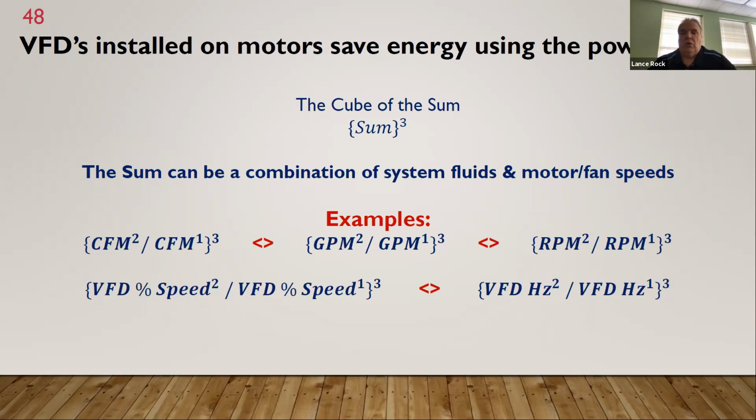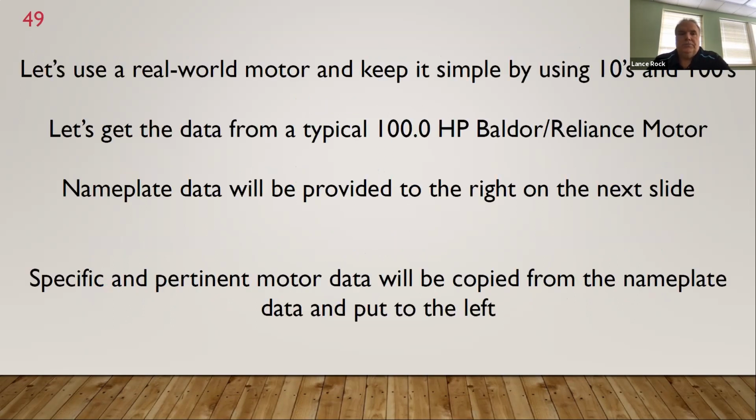Same with the 10 horse motor. From 100 to 80, you will save almost 50% of the watts/kilowatts used. That's the magic of VFDs. Next, please. I'm using the 100 horse that I talked about. I like using hundreds and tens for ease of understanding.